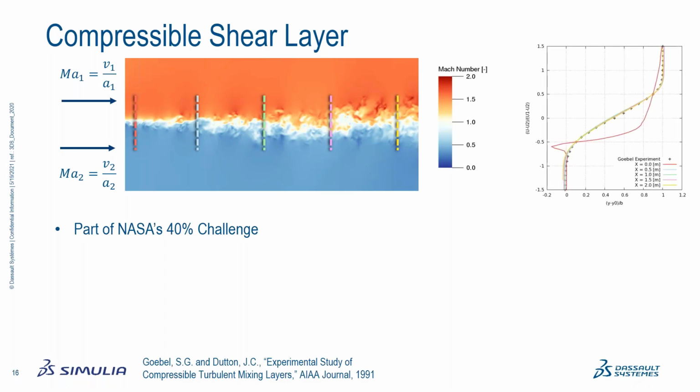As a first step, we can look at the velocity profiles at these 5 different sections. When we plot them and scale them accordingly, we can see that starting from the second velocity plot, all of the velocity profiles collapse to one single curve, which corresponds well to the experiment. So this means that the flow that we are simulating here is giving the correct results. The curve at the very beginning just shows the initial state of the shear layer, which is not mixed out. But once we travel downstream, the flow starts to mix, and then we end up with a well-defined curve.